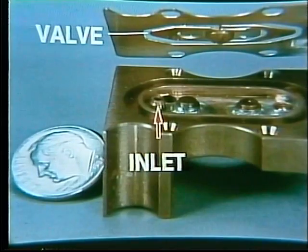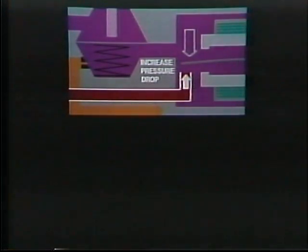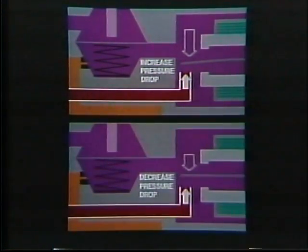The actuator valve is made small so it can move fast to improve drivability. In this disassembled part, actuator fuel comes to the inlet at system pressure. When assembled, the plate can be pulled toward the inlet to reduce the pressure of the inflow. The plate is controlled by a small electromagnet. More magnetic force pulls the plate closer to increase pressure drop by restricting the inflow. Less magnetic force allows the plate to rise to decrease pressure drop.